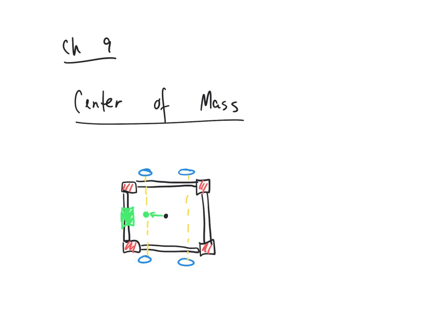You know this happens. Because if you step on something like a dolly, I wish I had a dolly in the room. Does anyone know what a dolly is? Four pieces of wood with wheels on each corner to move furniture, right? Not the upright hand truck, but the actual dolly. It looks like this. Because if you stand on the back of it, it goes. Yes. So put four wheels on a little dolly, right? That's what a dolly looks like. It's four pieces of wood attached. If you step on the very back of the dolly, what happens? It flops up, right? And it's flopping up like that because of the fact that you're now applying torque, really. You're causing rotation to it. But what you're really doing is you're greatly adjusting the center of mass of this.